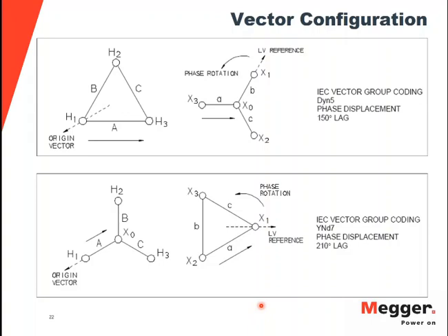So when you are first doing a test in the field, the best thing, what I always do, is a phase comparison to see if my A, B, and C phases are close to each other, because they should be relatively close and they should all be at the same temperature, unless you're measuring one day and another day. But most likely you're doing all three at the same time, so temperature is taken out. So it'd be good to do a phase-to-phase comparison with the winding resistance. But if you're able to correct for temperature, then you can always compare to previous results and factory results. Just make sure you're taking temperature into account.